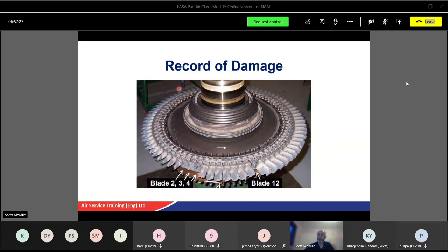This has also been taken out. They've inspected the engine, they've found the damage, they've disassembled the engine, and they've put the turbine on a stand. Actually, if you look at the bottom there, I think that might be the LP turbine still attached to it, and all the blades are missing because this bit has come off and trashed the turbine behind. And I've seen that before. I've seen an IP turbine blade, only 1 blade, a little bit come off, a clean break, and as it's gone back, it's hit the LP turbine and taken all the blades out. All you've been left with is little stubs like that. So, 1 little snap.